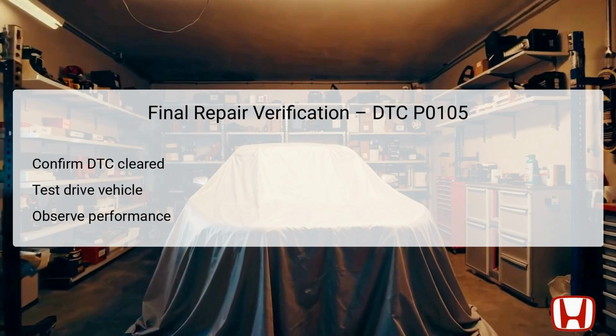The final repair verification step is vital to ensure that no issues persist after the repairs have been carried out. Once you finish the troubleshooting procedure and replace any faulty components, including the MAP sensor if necessary, the first action is to confirm that the DTC has been cleared successfully. Next, performing a test drive is essential to determine whether the vehicle now operates correctly under real-world conditions.